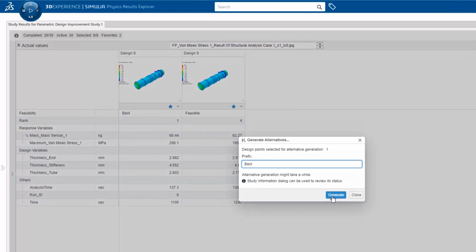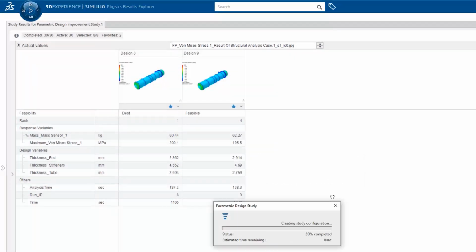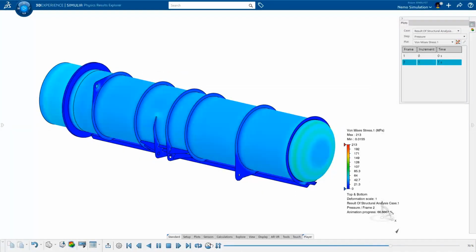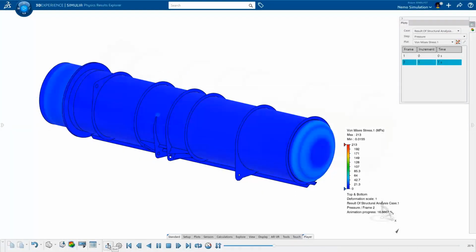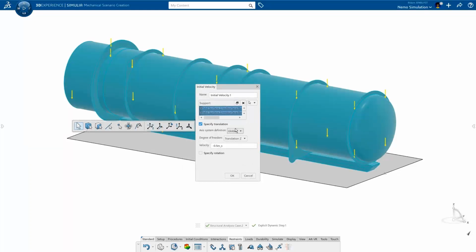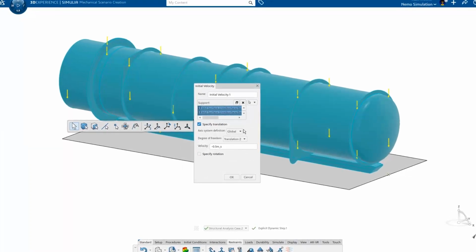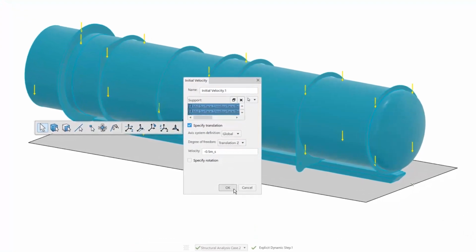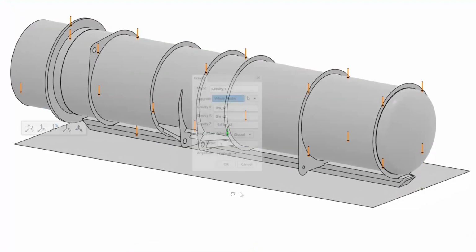But he has additional tasks to complete first. The pressure load on the battery compartment happens multiple times throughout the life of the Nemo. Another loading condition that repeats is the impact of the skid landing during storage. To simulate the secondary loading condition, Adam creates an explicit dynamic study to accurately capture the rapidly changing stresses of the landing cycle.